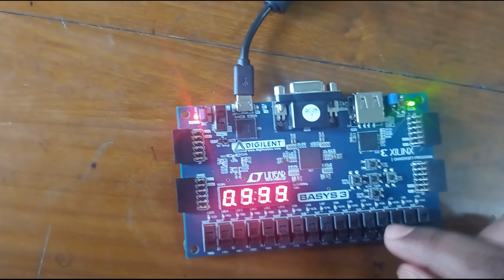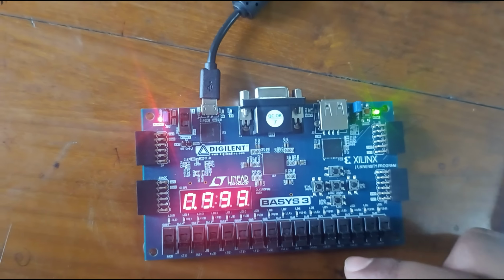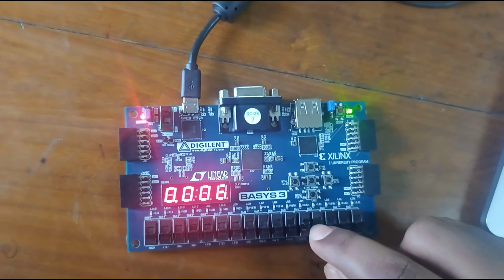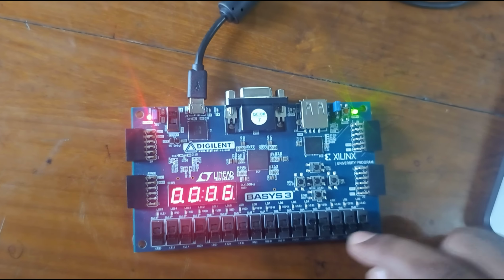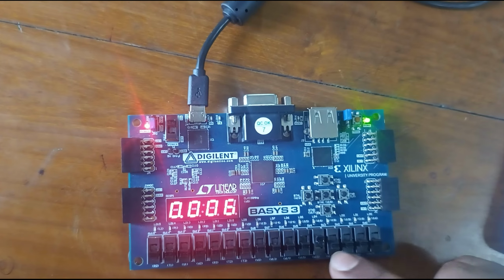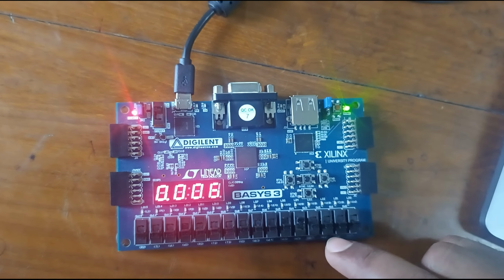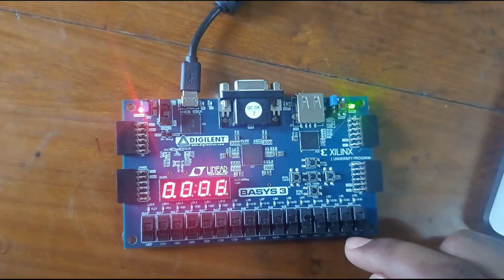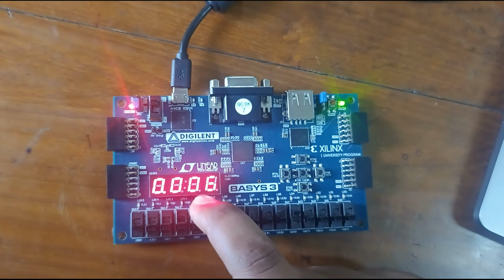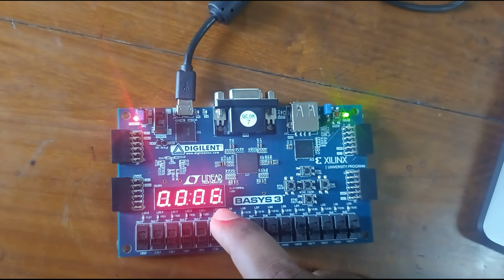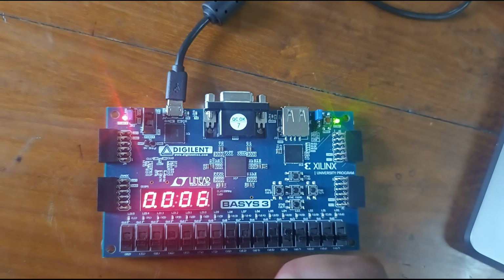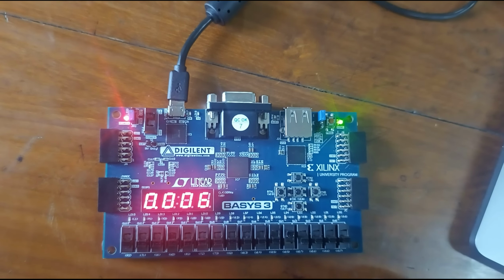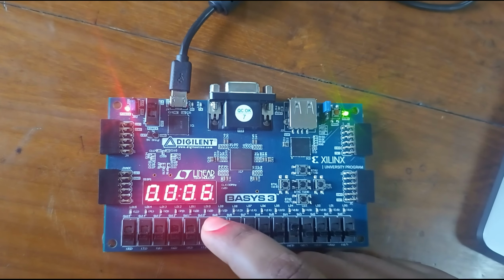If I want to calculate the sine function, I have to give it as 1, because I have declared 1 for sine and 0 for cosine. All three switches are for the degrees selection. If all are zeros, it will select 0 degrees. So sine 0 degrees will be 0.00. The remaining small error is there because the iteration count is low. If we increase the iteration count, it will get more accurate going further.